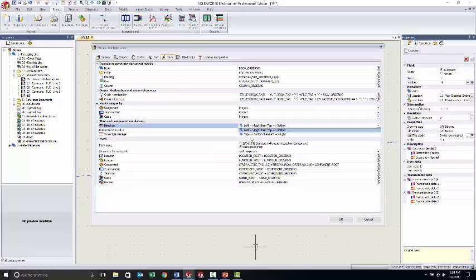That works the same for all of your component numbering and wire numbering. If you were using sheet number followed by row number, your row numbers would reset, and that resetting would trigger it to be a next piece.